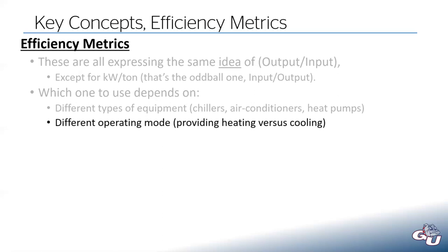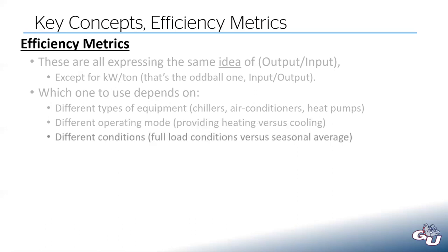Depends on your operating mode. If you have a heat pump, you're going to have an EER efficiency in cooling mode in addition to a COP efficiency in heating mode, depending on what the heat pump is doing. Different conditions, whether it's a full load condition or a seasonal average efficiency.